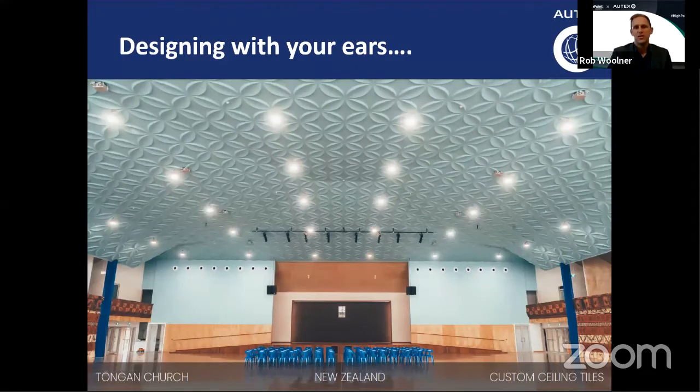The space here is a large church and prayer space, and we created it by molding our product into these large acoustic tiles. When we heat up PET as a panel, we can then, with pressure, mold it across a mold that we make, and it holds that shape afterwards. This is fixed onto a timber ceiling. This is glue fixed. Each individual tile makes up a frangipani flower, which was a theme here as a Pacific Island Church. Because the tile is 3D, it has an air cavity in behind it, which again enhances the acoustic properties.